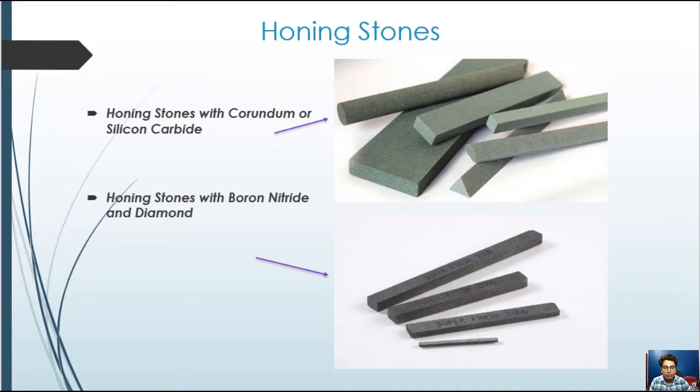In contrary to conventional honing tools, CBN or diamond honing stones must be adapted to the form of the workpiece prior to use. For the honing of bores, for example, the tools are ground to the dimension of the hole in a pre-tension state on an external grinding machine with silicon carbide or precious corundum grinding wheels. After this profiling process, honing tools have no cutting efficiency, so that a downstream sharpening process is required.